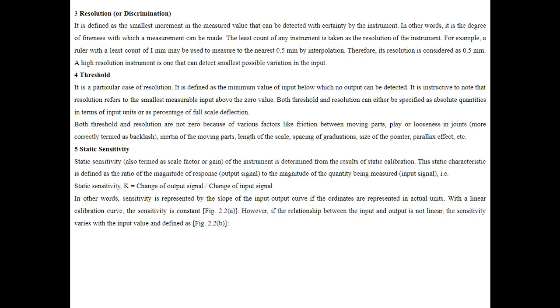Next is threshold. It is a particular case of resolution. It is defined as the minimum value of input below which no output can be detected. It is instructive to note that resolution refers to the smallest measurable input above the zero value.